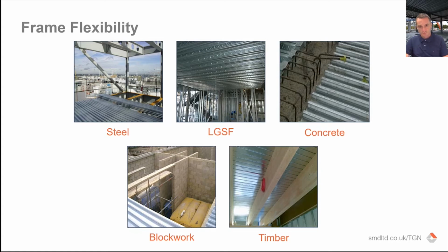From the point of view of our floor deck products, we have R51+, TR60+, and TR80+. These are shallow floor deck profiles. They can be installed on many different structure types, so frame types, whether it be steel or light gauge. Steel is naturally the most popular, and that is due to the use with composite construction and shear studs that I mentioned earlier, and we're going to look at those details. It is also very popular in light gauge steel frames, so load bearing light gauge frames where the walls go up, and we're going to see a detail on that later.